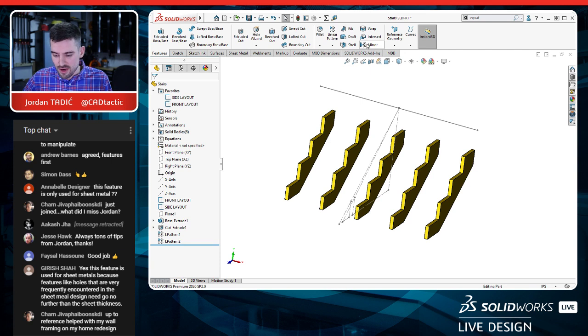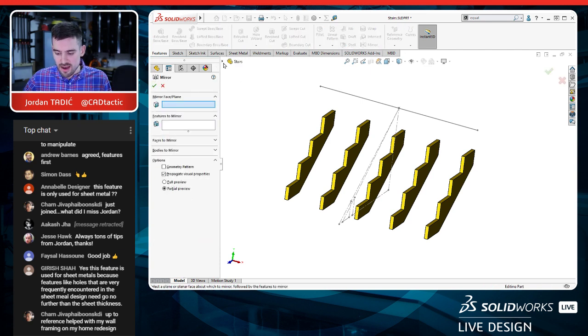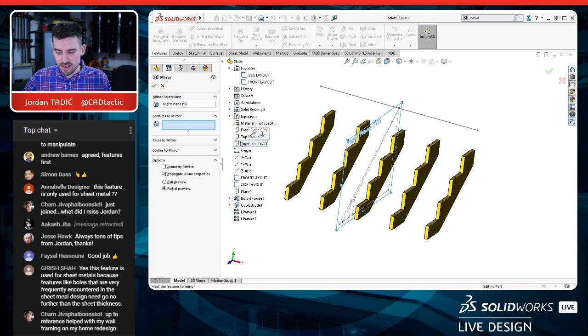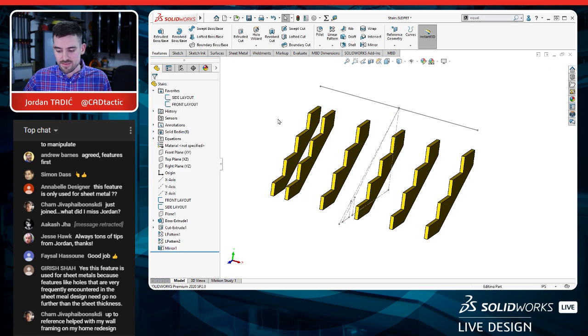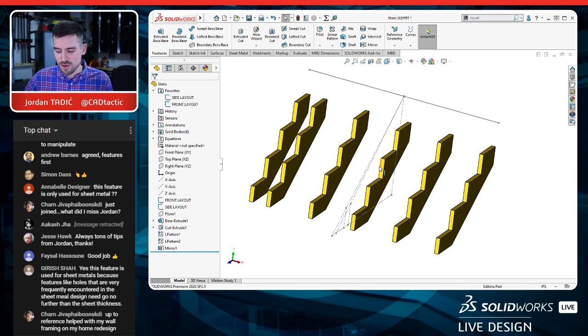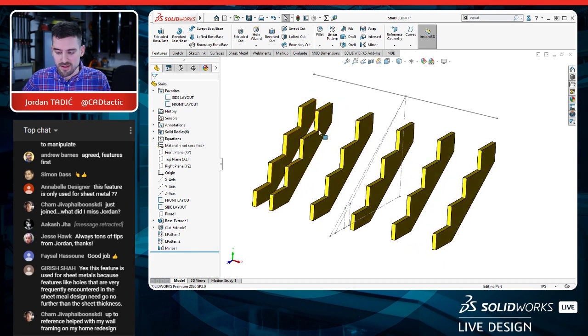And I'll also fire up the mirror command because I want to mirror across the right plane this very first, once again, body, not features, but this entire chunk of material over to that side. We're looking good. You might think, well, why don't you evenly space those out? You don't have to in this scenario. And actually, most people prefer not to because once you cover this up with the tread plates and the kick plates, you won't be able to see those. And now you'll know every 16 inches you can screw or nail down. So that's totally fine having that smaller gap right there.